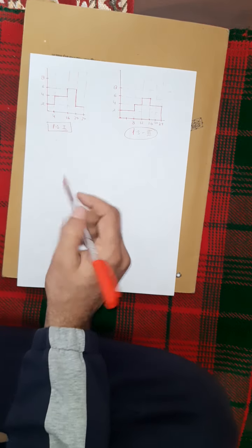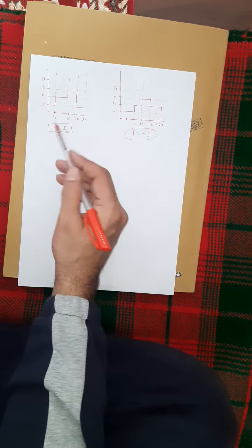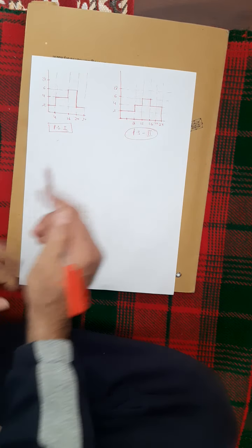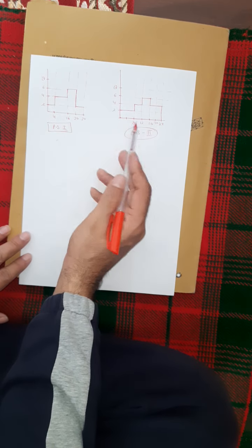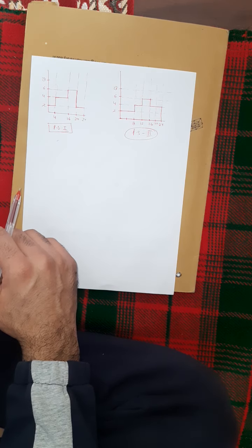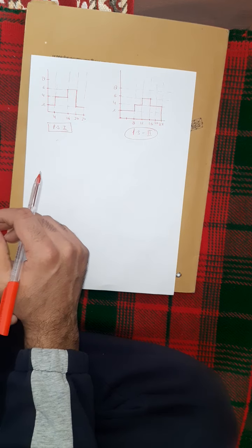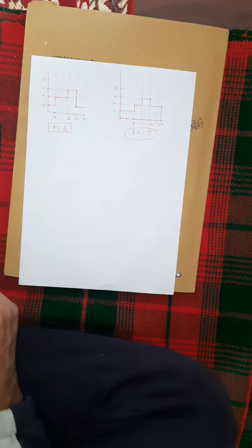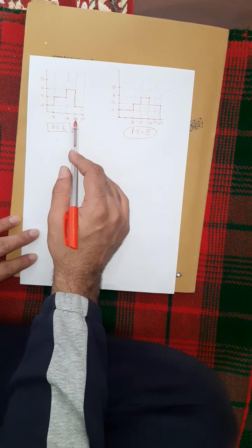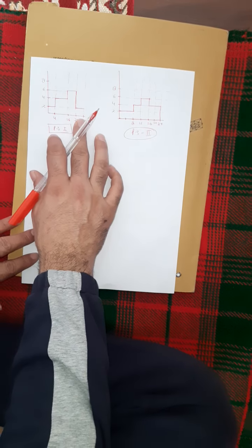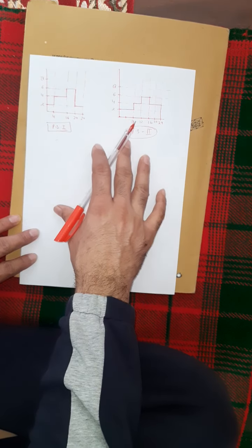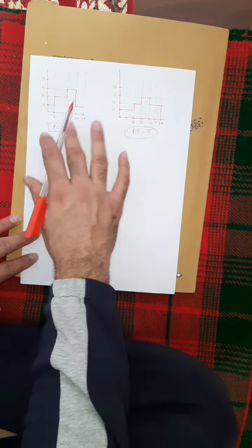So what I was saying is, the load curves of interconnected power stations are likely to differ. Like here, I have two power stations and the load curves are here. Now I am saying these two power stations are interconnected, and I have to draw a common load curve of the interconnected power stations. The result is that when they are interconnected, the maximum demand on the system is much reduced as compared to the sum of the individual maximum demands of the two power stations.